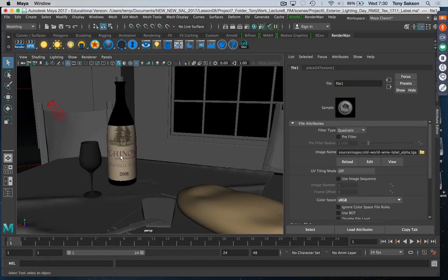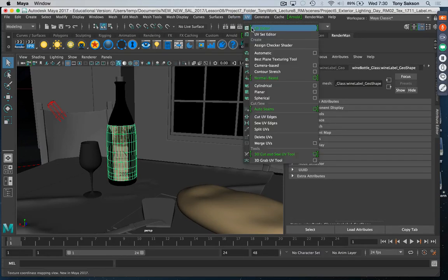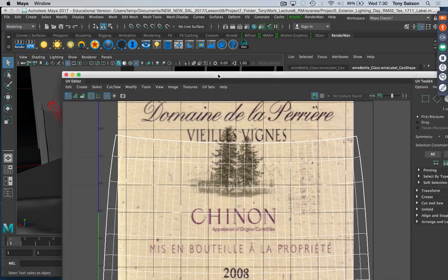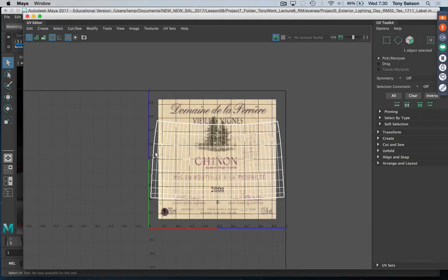So, to rescale this, we're not going to go back into Photoshop. We're not going to pull any kind of place 2D coverage voodoo on it. What we're going to do is simply select the geometry and go into the UV editor. So notice it does cover the entire 0 to 1 space, and our teeny, puny, human-looking UVs just dwarf compared to it.